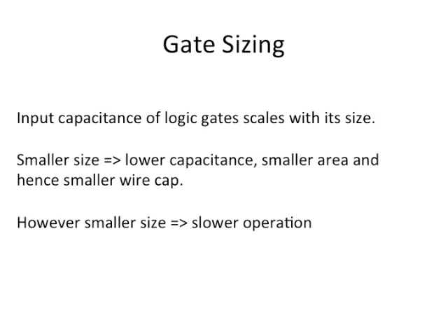Gate sizing: we saw that the capacitance is there in the equation for dynamic power dissipation. To reduce capacitance, you reduce the gate sizes. When you reduce the gate size, it has another side benefit, which is that things have become smaller, so you can keep them perhaps closer. So wire capacitance can also come down. So gate sizing is another very powerful tool to try to reduce power. But with sizing, as you might recall, size affects the speed because size affects the drive current, so there is a trade-off with sizing between power and performance.